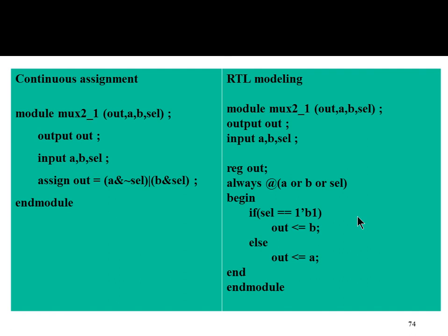This is a non-blocking assignment. And why would that be? Because of the if statement: if the select line is one, then it's giving the output as B for the first cycle, and if it's not one, then it would be A. Yeah, but we don't have any clocks here, right? Sorry, this is a blocking assignment. It's just comparing the condition and giving out the output. It's not giving output one at a time. So that's a blocking assignment.